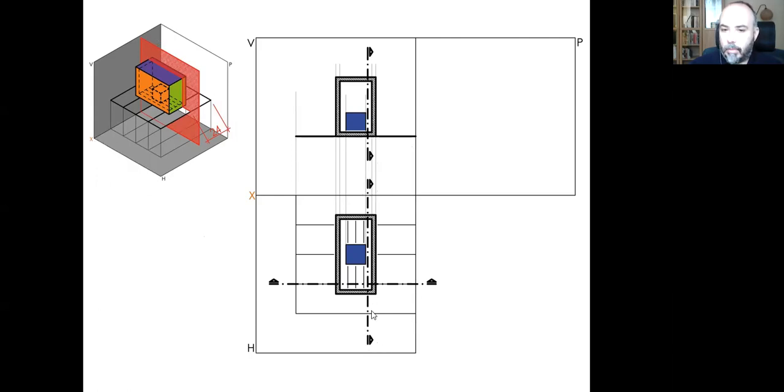Again, please do not forget, I am using 3 line weights and in order to indicate that something is being cut, I prefer the thickest line that I can create and the most black one.